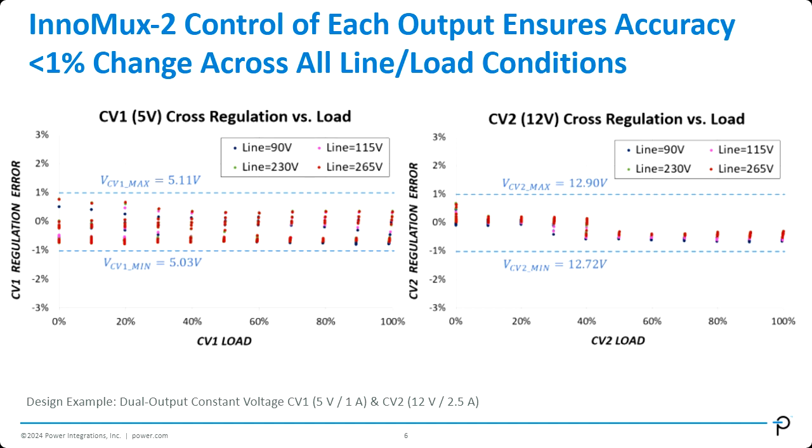But if we use a 5 volt and, for example, 48 volt in this case, normally we're limited by the primary side VOR of the top output. So the 48 volt VOR is, for example, limited to 150 volt. But then if we use a single winding, the 5 volt VOR would be as low as 10 to 20 volt. If that's the case, your system might enter really deep CCM operation that might not be good for component stress. So yeah, really it depends.